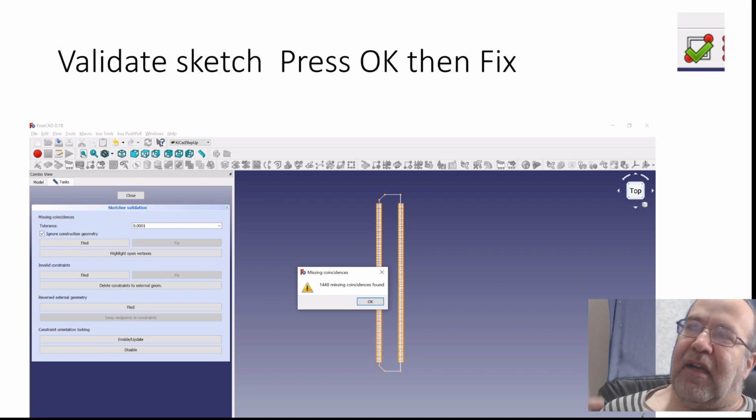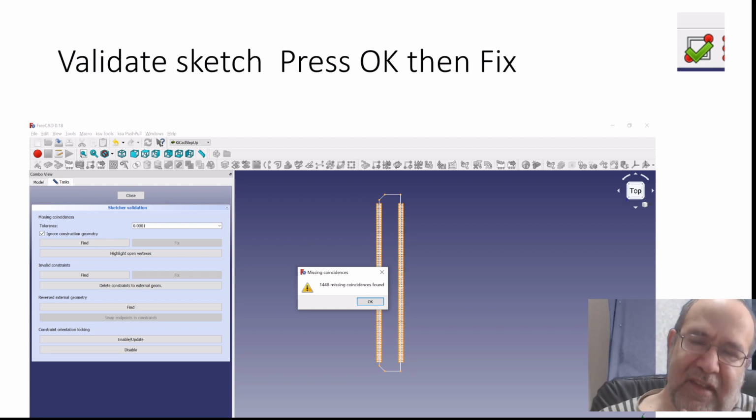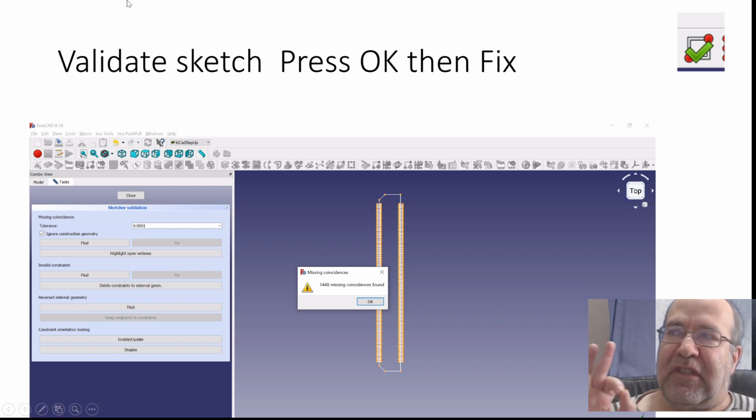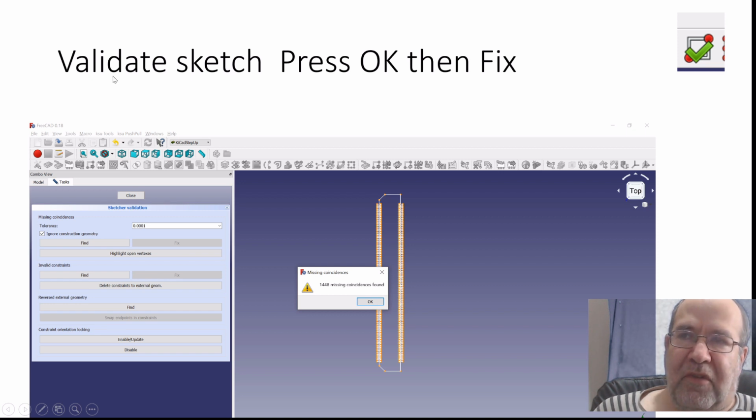So here I'm running through and fixing the lines so that they'll be coincident, basically connecting the lines if they are very close together. Okay, it is a problem when working with DXF files exported from mechanical engineers.